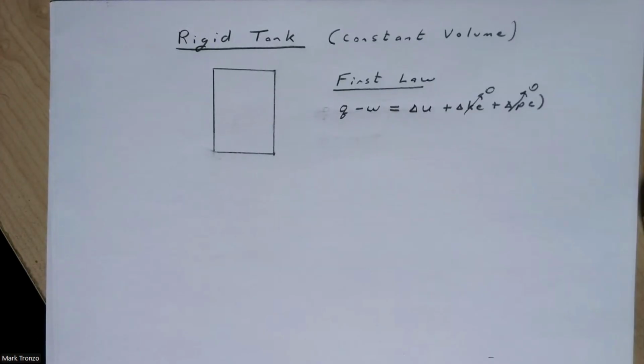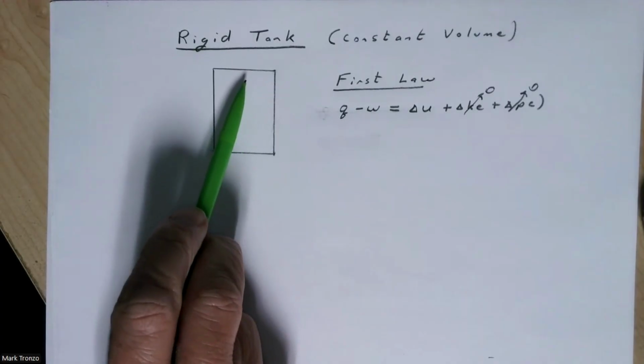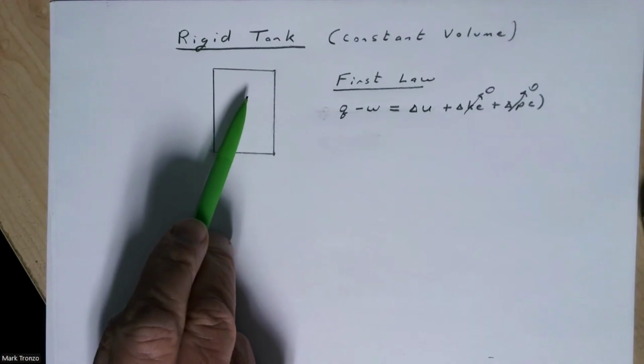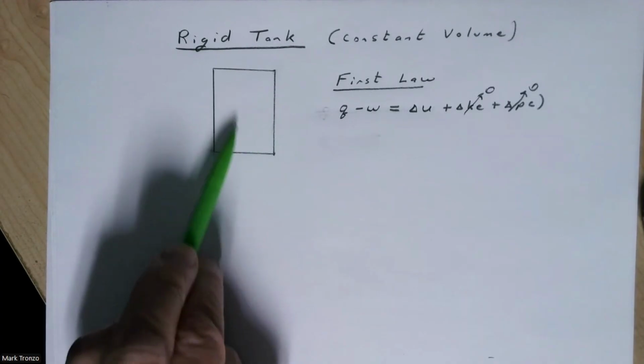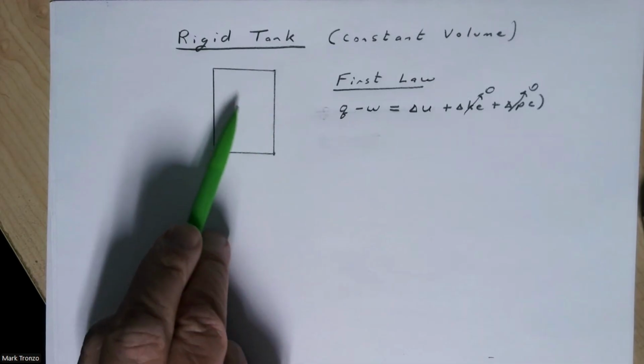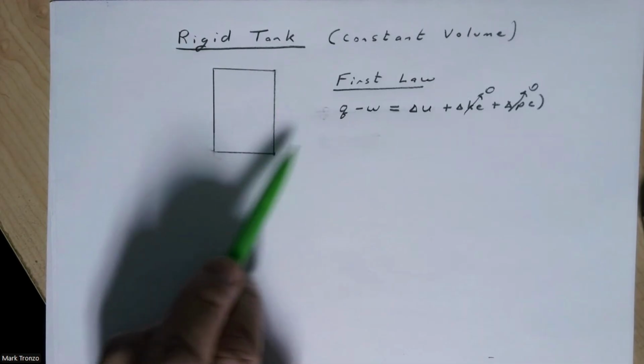In this video, we're going to look at rigid tank applications. Again, that's going to apply constant volume application because if the tank is rigid, there's going to be no boundary work, so the volume is not going to change. The boundary is going to remain fixed.